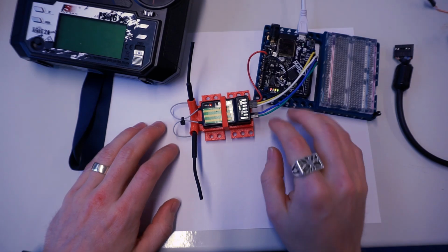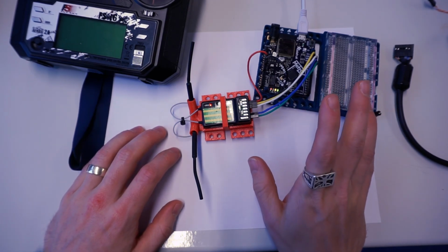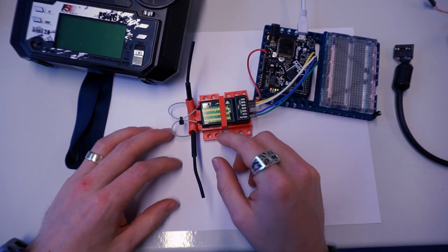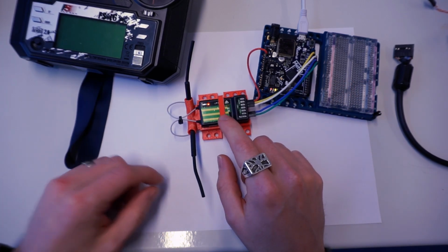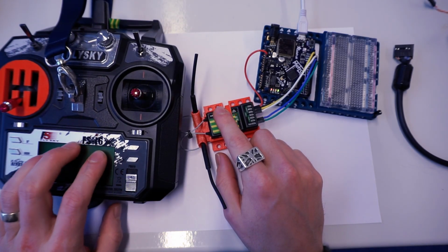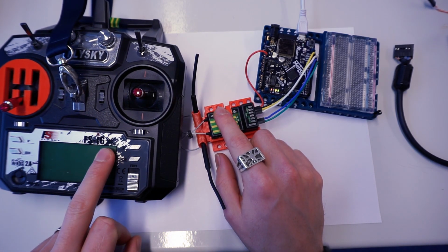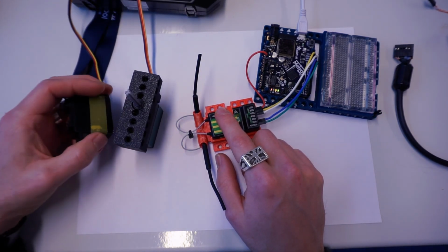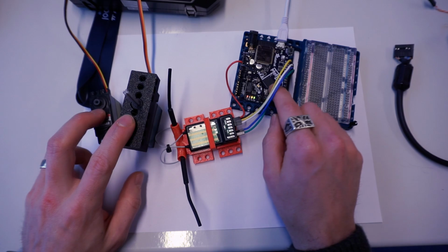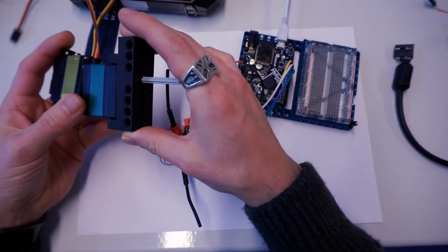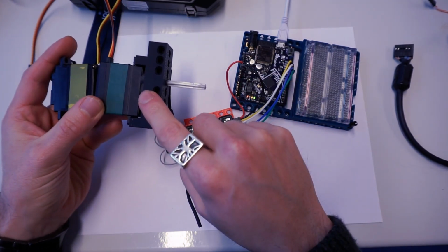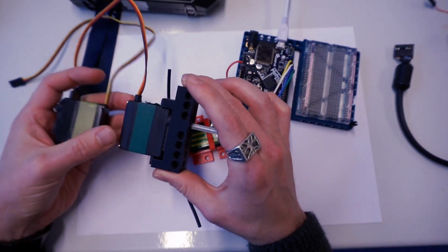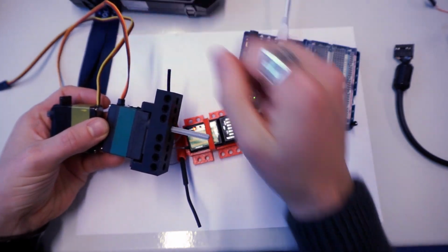All right, so wiring. This project assumes a couple really important things. The first, it assumes that you're using the FlySky controller and the library that I've written up for that. You can see that in the description down below. It also assumes that you're using a FlySky i4, i3, i6, or i7 receiver. It also assumes that you have two continuous servo motors connected to your microcontroller somewhere in a tank-style drive on your Rover. So one side of your Rover is controlled completely by one motor, the other side is controlled by another. So a really common setup, you may have something like this and a caster setup.